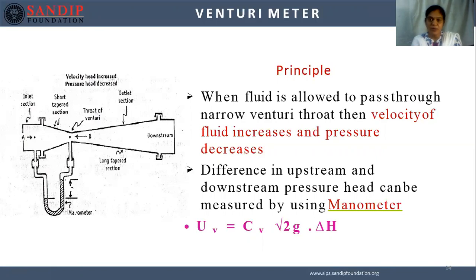Again, you have to keep it in mind, this Venturimeter has to be placed in between a long straight pipe, so that the other fittings will not alter the flow rate that is being measured. The upstream cone is normally shorter than the downstream. Okay. So here the tapers are to be smooth as well as gradual.